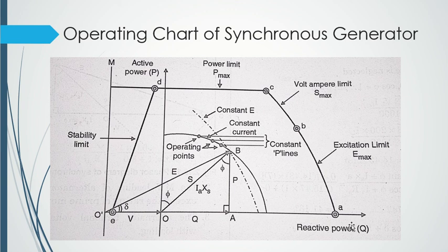See, this is the limit of your armature, this is the limit of your alternator, and this point B should be within this area bounded by this curve. As long as your point B is inside this curve, your armature will be safe. As soon as my point B exceeds this area or surpasses this curve, at that time my armature will be at risk.